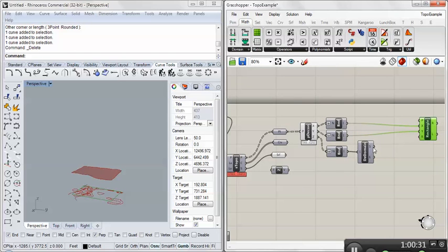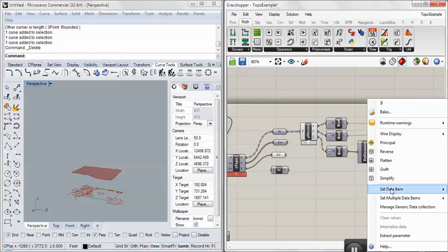So I'm going to go ahead and make a point here. I'm using the point at the minimum elevation as a starting point, and I want to go down 200 feet, so I'm just going to subtract. It's under math, operations. It's going to take that start elevation, map it to A, and then right click and set this data to 200.